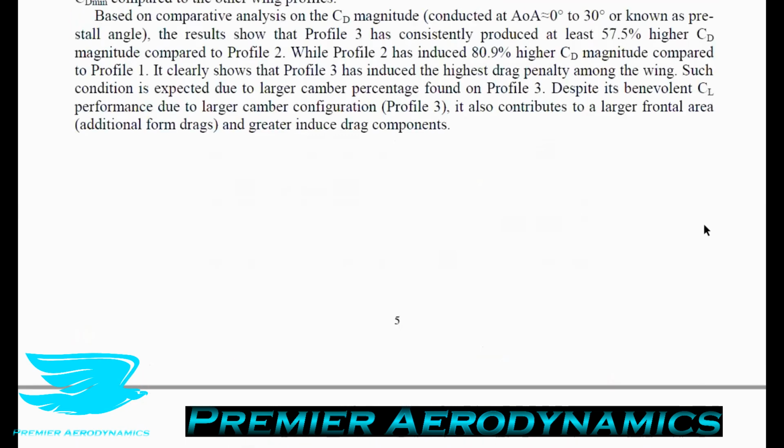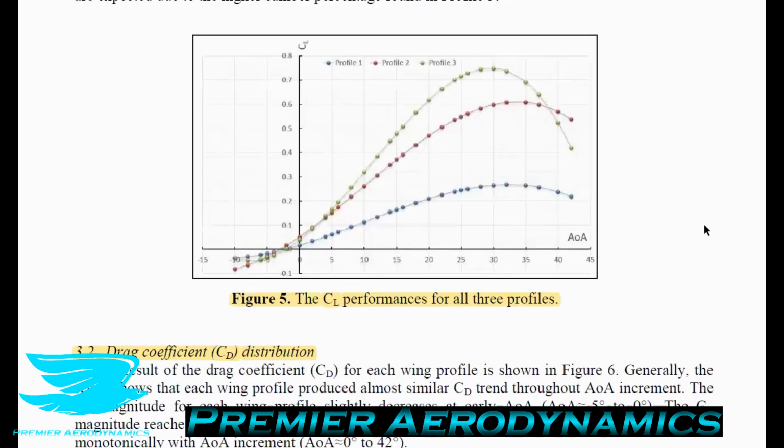So they also have fairly agreeable stall characteristics, where you don't have this massive drop off in lift once you reach a certain angle of attack. It's more gentle. So these are all very beneficial aerodynamic properties of Zimmerman airfoils and how they are different to most other airfoils. So for most other airfoils, when you reach the stall angle of attack, the lift will reduce dramatically. Some airfoils are stable in terms of their pitching moment, others are not. And also the lift being produced at low Reynolds numbers is fairly low for most airfoils, and you also result in a very low stall angle of attack.